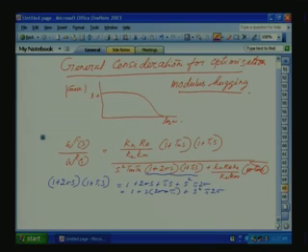See here, these are filter time constants T1 and 2 sigma, that is because of the current control loop. These are smaller time constants compared to our electromechanical time constant. Because this is coming in a loop where the maximum response depends on the electromechanical time constant, we can neglect this on practical purpose, and approximately represent it as a first order lag, 1 plus delta s, where delta is equal to 2 sigma plus T1.